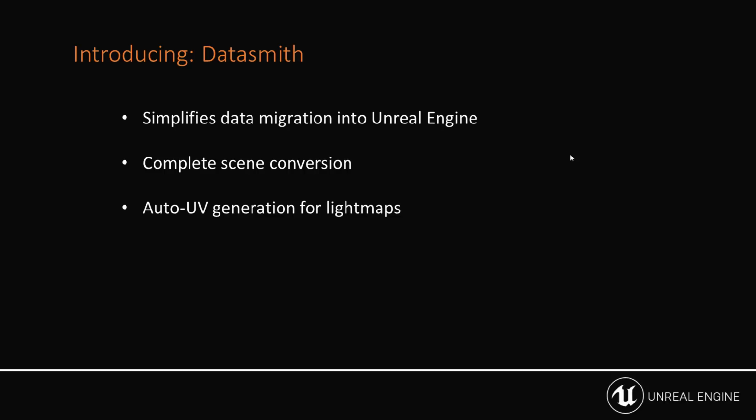So what Datasmith sets out to do is solve those problems. It's kind of twofold there. I don't know what UVs are, so the auto UV generation takes care of that for them. But also, you might have thousands of objects, 2, 3, 10,000 objects in that scene. It's a lot of work to put UVs on. So this idea of having auto UVs generated to bring over into Unreal Engine, into your scene, takes care of that for you. And again, of course, hero assets that might have logos or specific liveries on them, specific details, those are going to require a little bit more of a manual overview, a manual look, to make sure that they come over fine and texture fine.